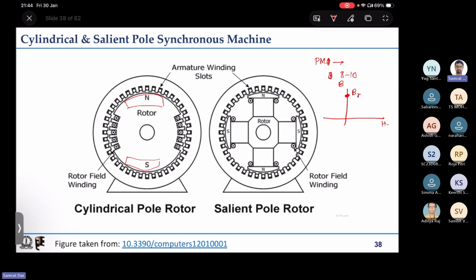That is a permanent magnet. Another thing is, even if we apply some negative H towards it, the B will reduce, but it should not demagnetize very quickly. Another important thing is coercivity, that is Hc. At what negative field does the remnant flux density basically go to zero, or the magnetic property of the permanent magnet goes away? This characteristic in the second quadrant is known as the demagnetization characteristic of permanent magnets.